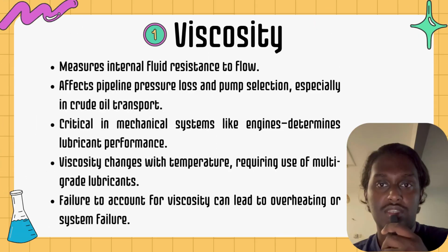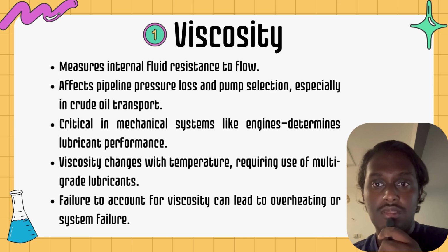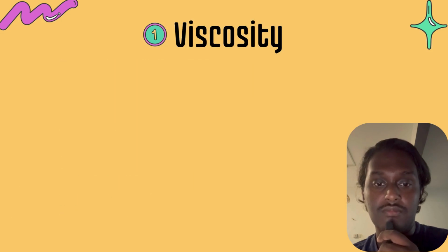Firstly, viscosity. Viscosity is a measure of a fluid's internal resistance to flow. It affects pipeline pressure loss and pump selection, especially in crude oil transport. It is critical in mechanical systems like engines, and it determines the performance of a lubricant. Viscosity changes with temperature, which requires the use of multi-grade lubricants. Failure to account for viscosity can lead to overheating or system failure.